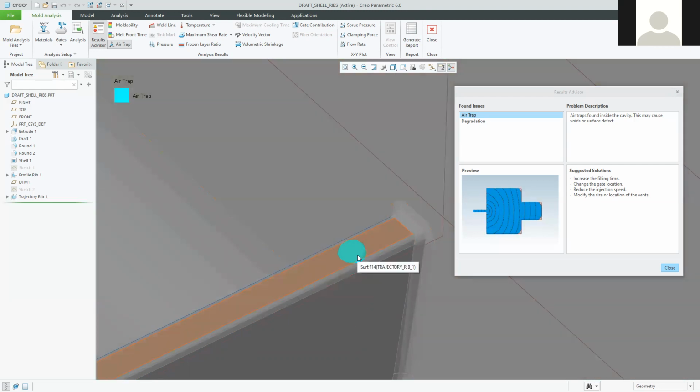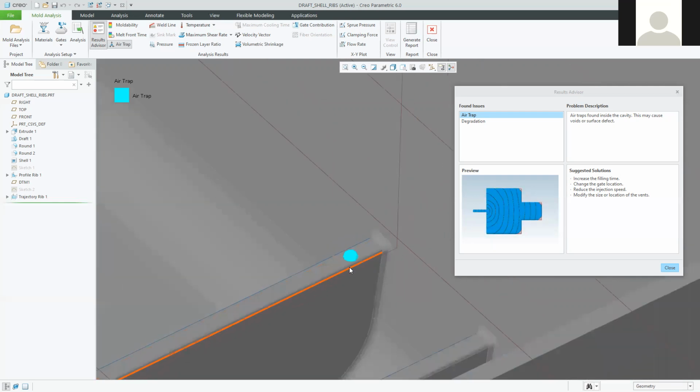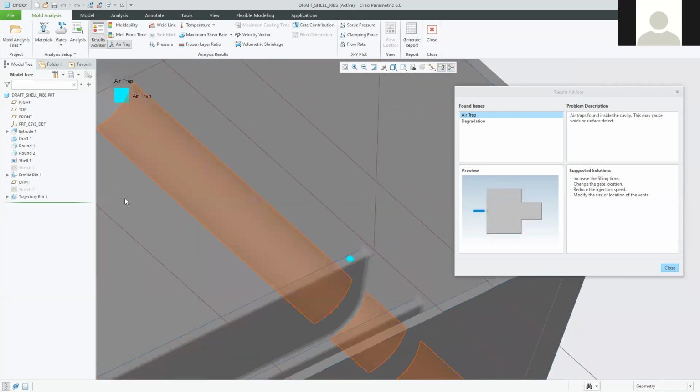So it's almost like a runner or a sprue that sticks out there, knowing that the air is going to congregate there. That little sacrificial piece of material may have voids in it, but it's intended to be discarded or recycled, more likely. So that would be one solution. Then maybe I would run it again with this, let's say, thin cylindrical piece of material that sticks directly up out of that face at that point.